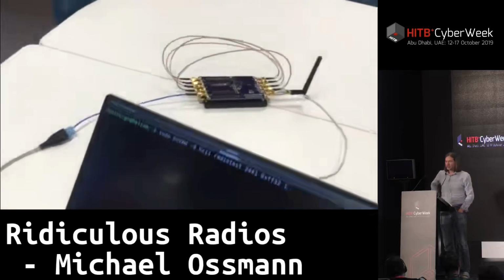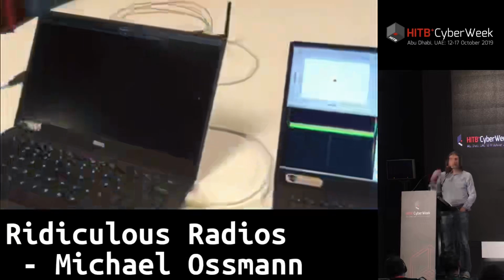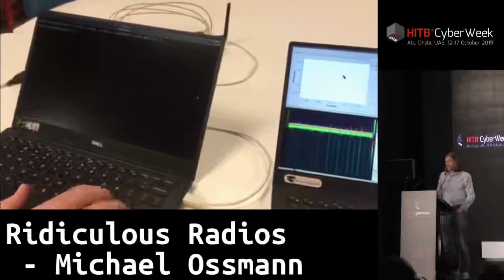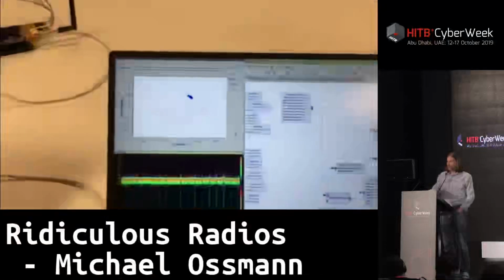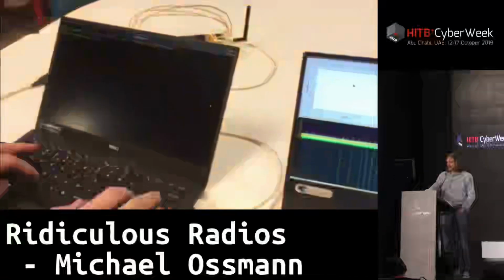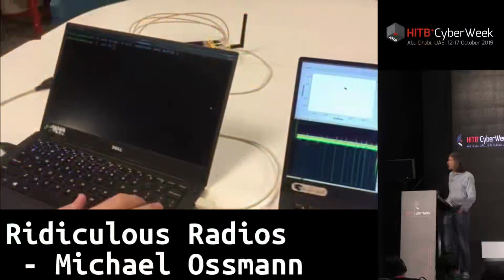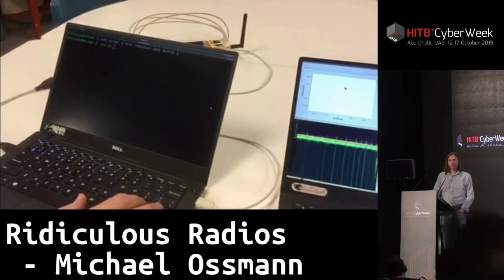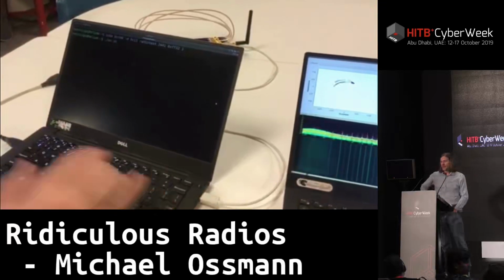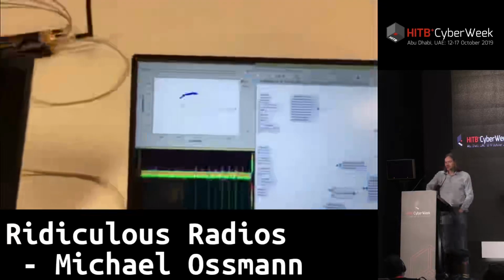And so he's going to transmit a signal without switching its phase randomly. And you can see in the upper left-hand corner of my screen that there's this blue dot that indicates the direction of that signal. I'm detecting the direction of his signal. And then he's going to turn on his script that starts randomly modulating his phase by switching back and forth between 2 different delay lines. And look what happens to my direction finding setup.